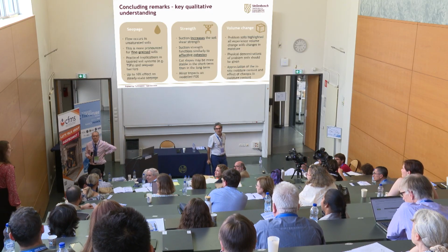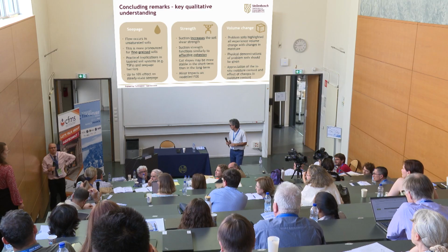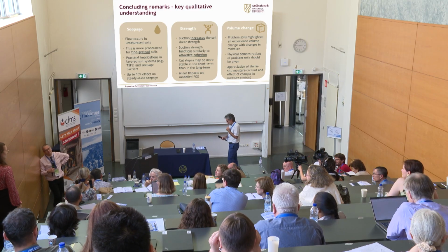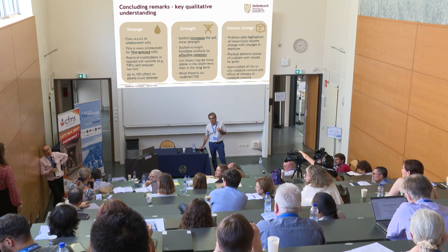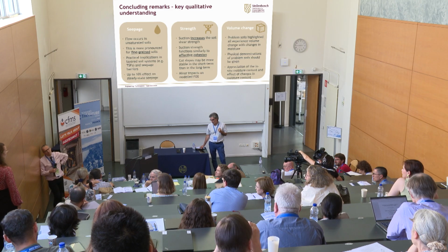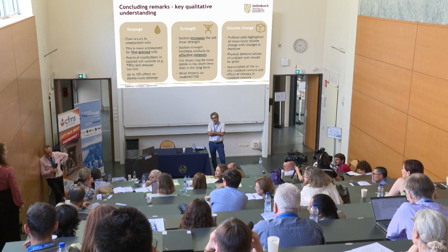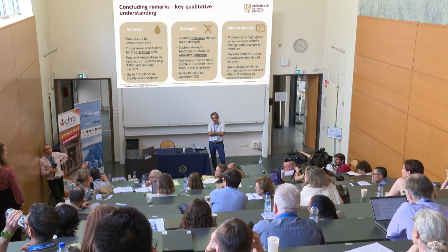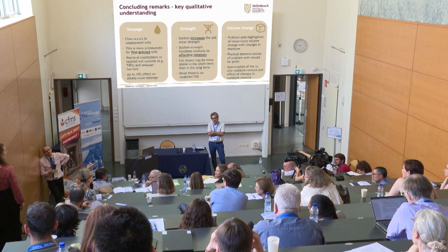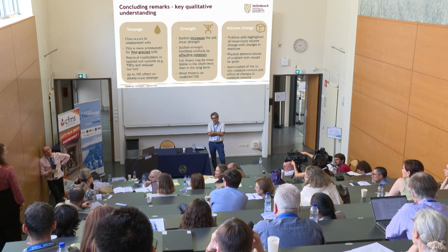To add a consideration: one thing that I see my students struggling with is that they have in mind this duality, dry or saturated, with nothing in between. Sometimes I ask them to calculate total stress with depth, and for the soil above water, they use the dry unit weight, and they are convinced of that.